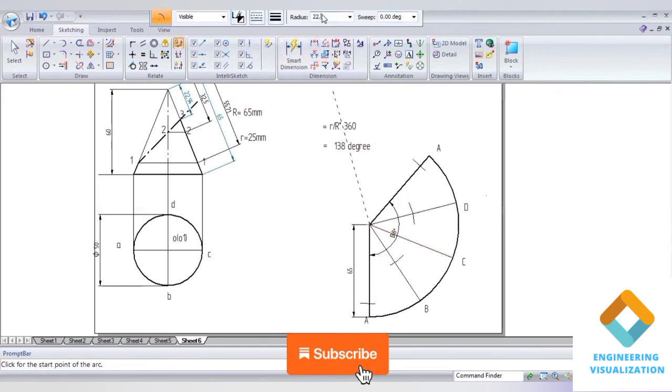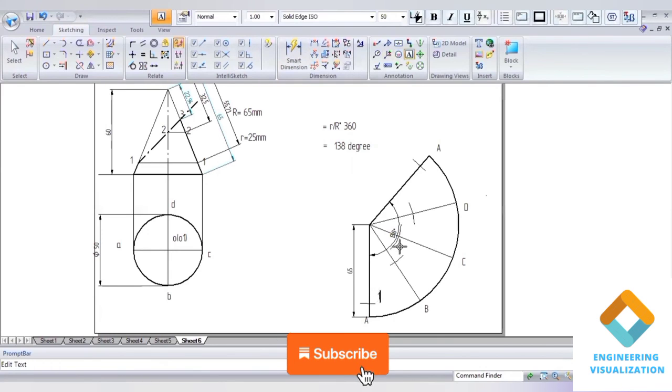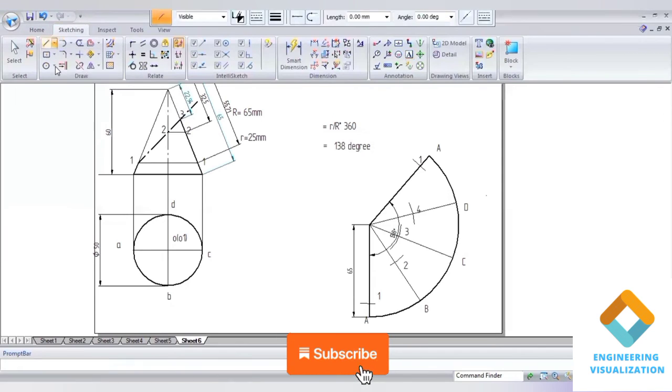So give the radius. Okay, cut it. Now I can write the naming for it. So this is 1, this is 2, this is 3, and this is 4, and this is 1 again. Now connect all these points using the curve command here, because this is a cone. So go to arc and go to the curve command and connect all these points. Okay, go to the curve command here.